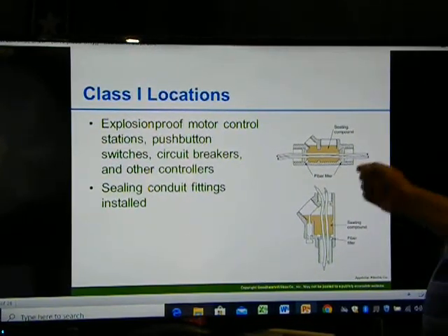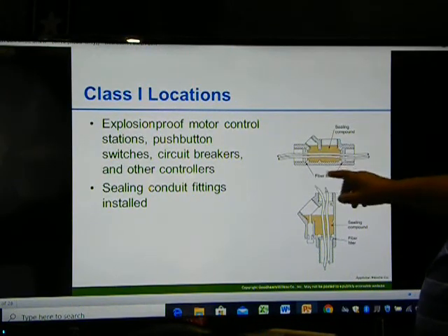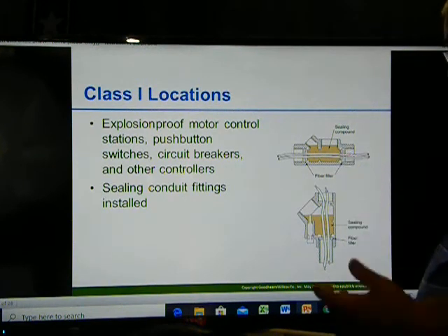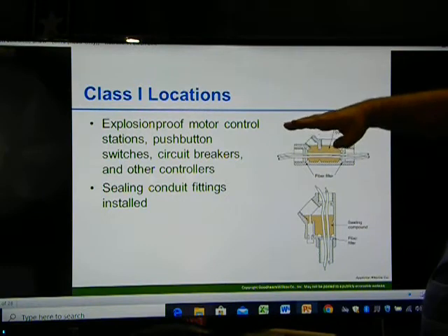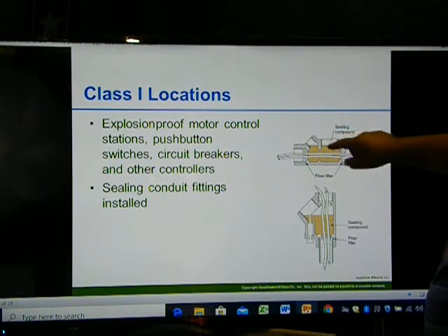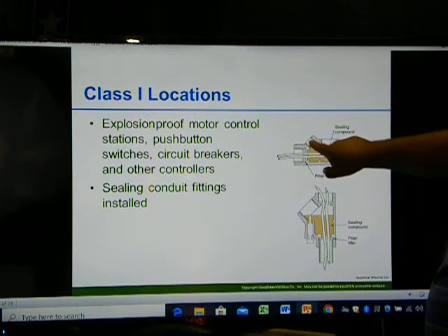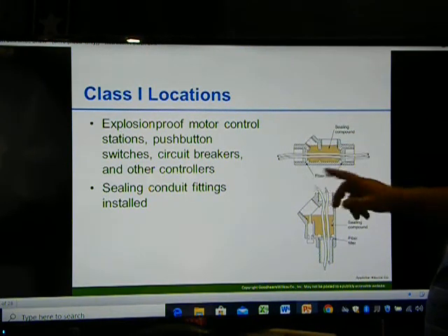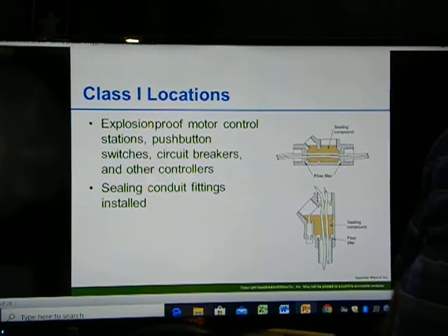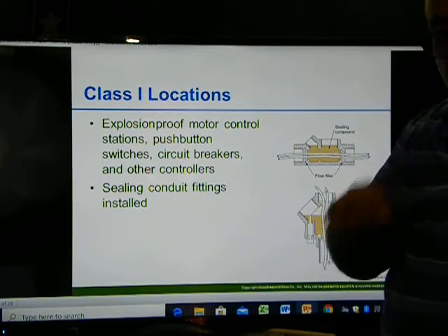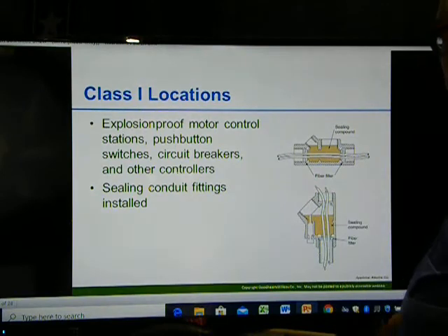And then you go back, once you get the wire pulled in, and you put all your seals in. There's a fiber you stick in here, there's a fiber you stick in here, it's a dam. So this is going this way, so I have to dam up both sides. I can put in the plug, seal this off, and then fill it in to here. You fill it up once it gets to the hole, and then you're done. Put your plug in, and you're done. We used to use a little stick and poke it to make sure it got in there real good.